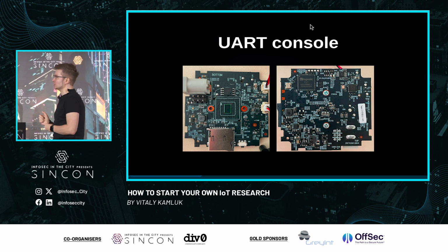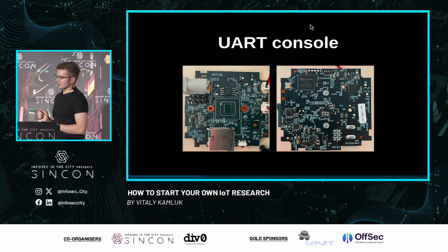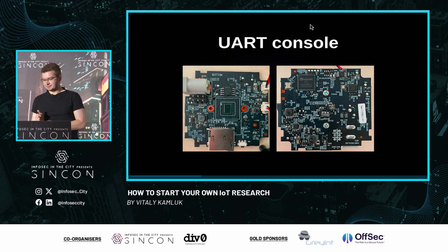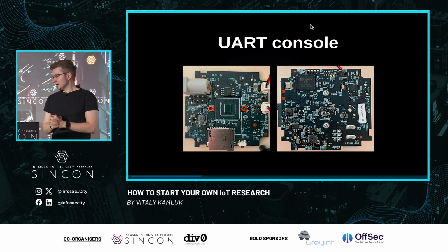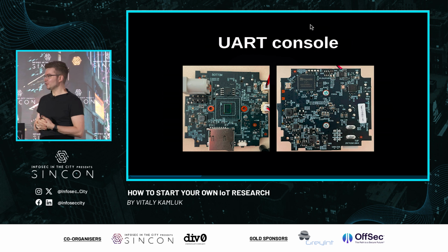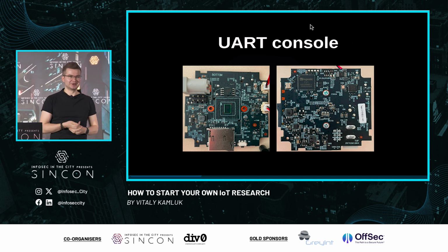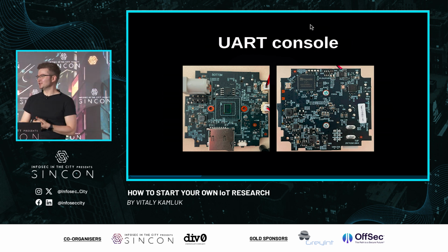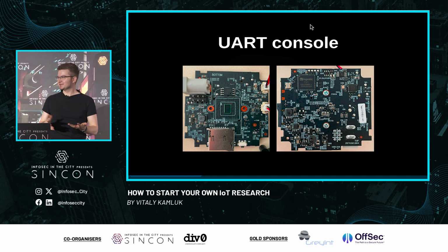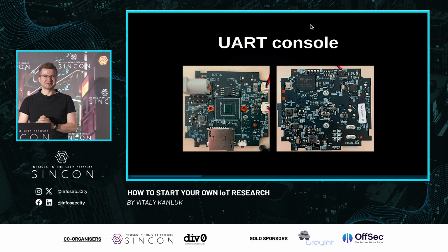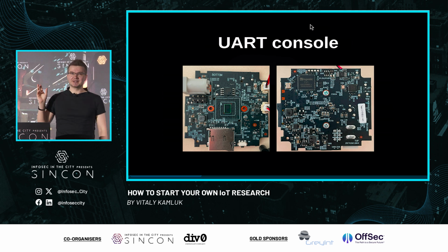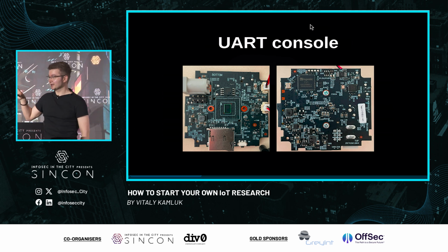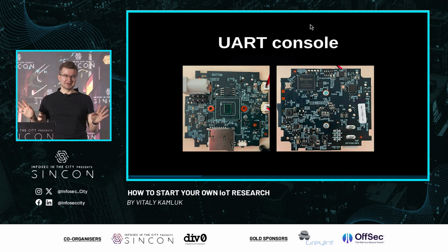So there was nothing that looked like UART pins, and that takes 4 or 6 pins, depending on the configuration. So I tried to brute force all possible pins that I saw there. I tried to deduce where this UART is. Does it even include UART? Because previously it was there on some older variants of the same camera. They actually had it marked, but on mine there was no sign at all.